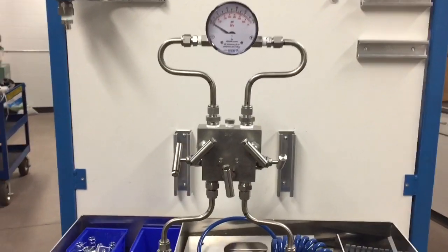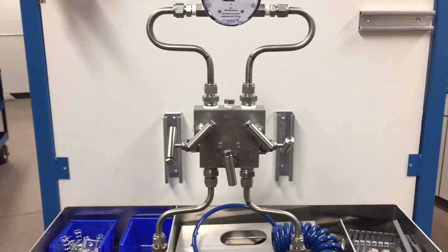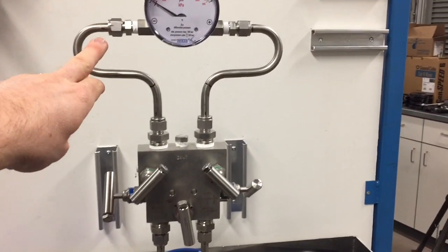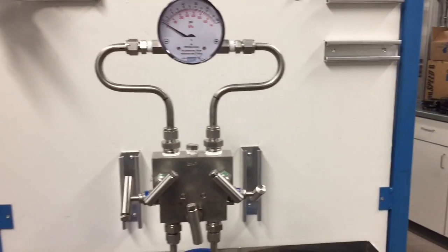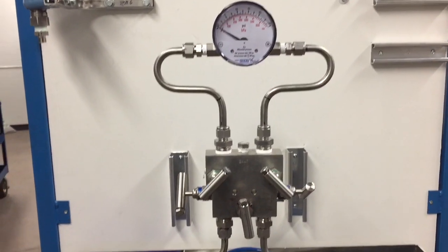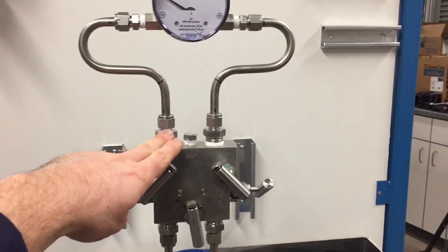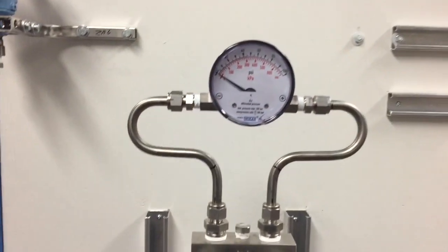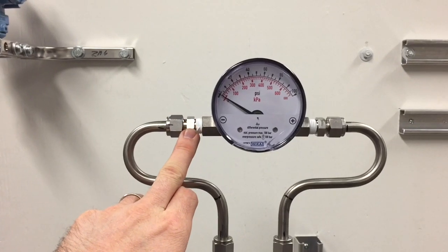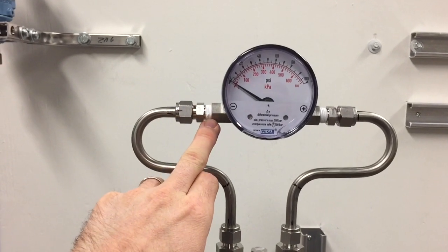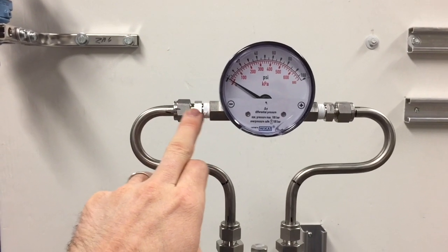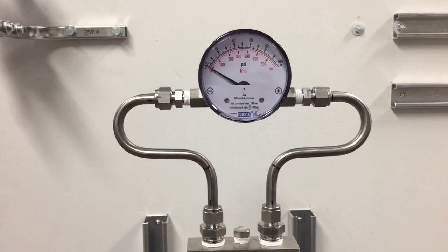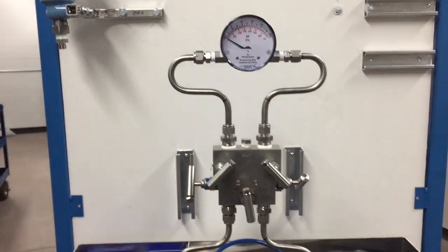So this has been installed correctly. All right, now for our cleanup, we're going to disassemble all of this and cut all of our nuts off of our tubing to reuse them. But these fittings on our manifold can stay. The fittings on the needle valves at the bottom there can stay. But we will remove the 3/8 tube by 1/4 inch NPT threaded fitting here on both sides of the gauge. So we're going to go ahead and remove all of that now.